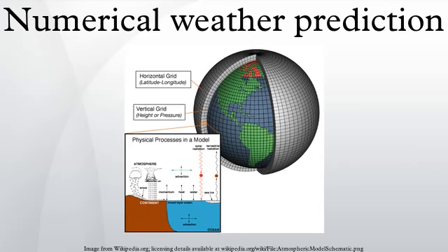Applications. Air quality modeling. Air quality forecasting attempts to predict when the concentrations of pollutants will attain levels that are hazardous to public health. The concentration of pollutants in the atmosphere is determined by their transport, or mean velocity of movement through the atmosphere, their diffusion, chemical transformation, and ground deposition. In addition to pollutant source and terrain information, these models require data about the state of the fluid flow in the atmosphere to determine its transport and diffusion.